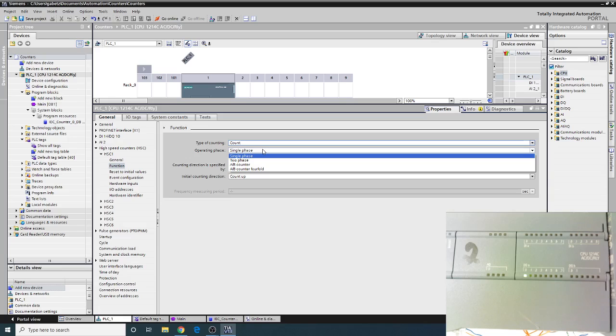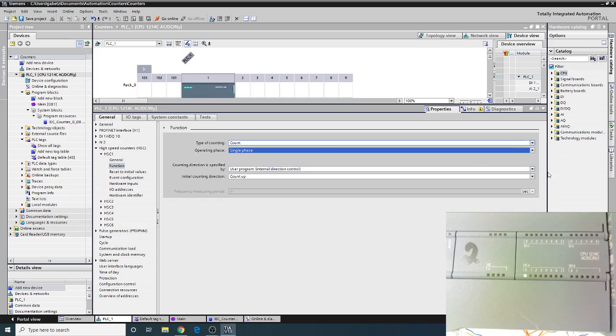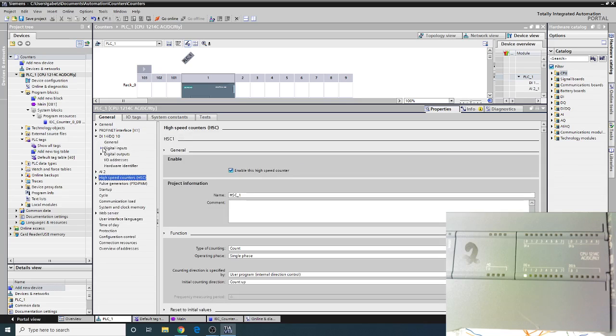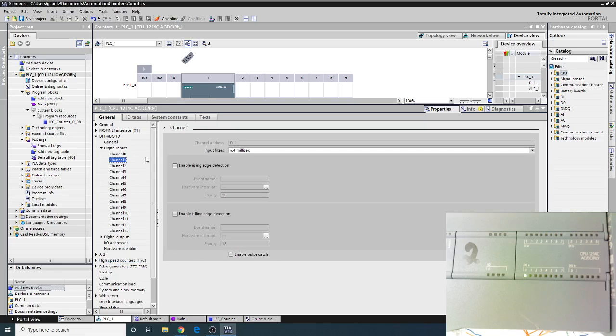Traditionally, especially in larger PLCs, the high-speed counters are going to be their own module. So if you need to do high-speed counting, you'll buy one of these modules, slap it on your modular system, and you're good to go. With this one, we overall actually do have 6 of them built in. Now, one thing we have to do if you're going to be using a high-speed counter, which again, we're not really going to be playing with this semester, but I do like to talk about them.